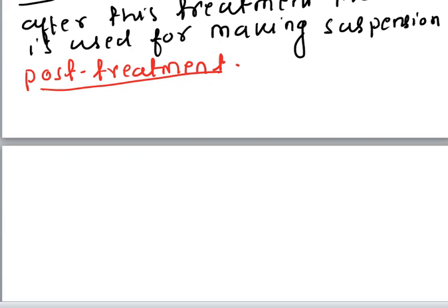In this case also there is flock formation, where the fine soil particles aggregate with each other and form flocs. So to deflocculate them, such that the settling is in accordance with Stokes law, that is type 1 or discrete particle settling, we have to add a deflocculating agent which will segregate that aggregation. Okay, so we have to disperse them.